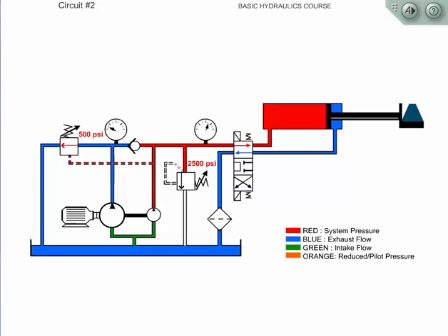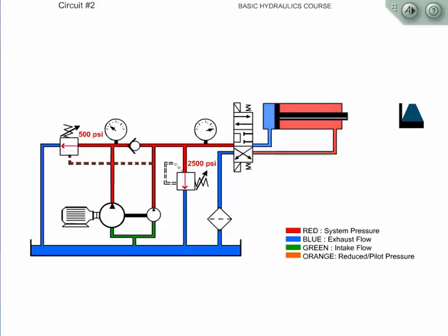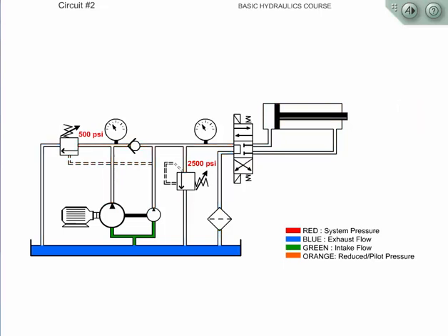The pressure will continue to rise until it reaches the relief valve setting. When the directional control valve is reversed, the pressure drops and the unloading valve closes. The cylinder would retract at a rapid speed. Now let's examine more closely the components that make up this system. First, the unloading valve. This valve has been set at 500 psi.